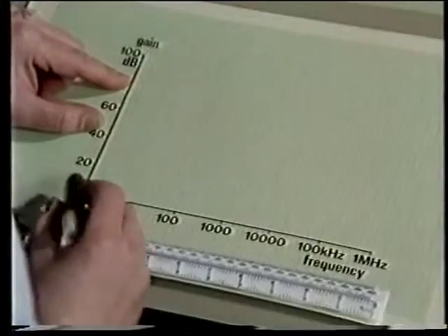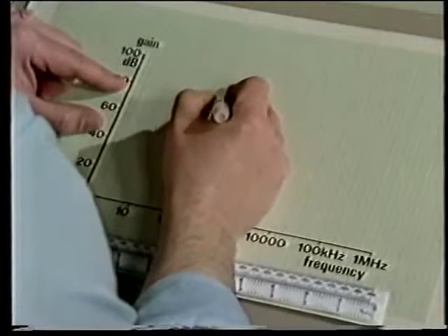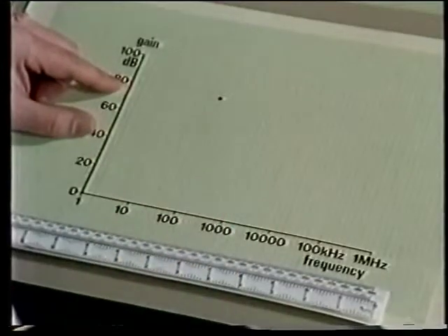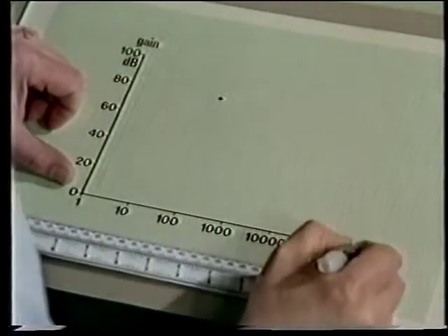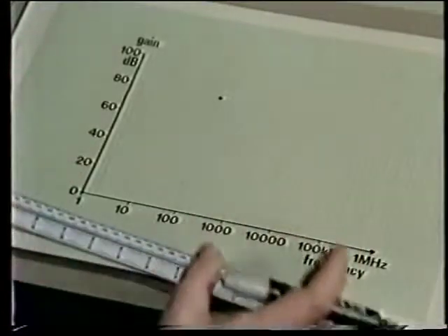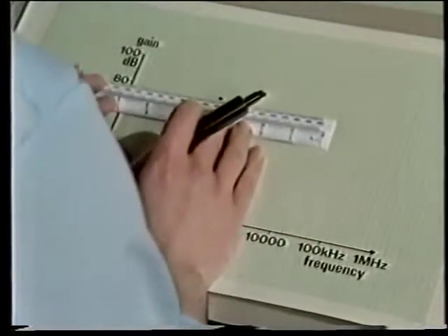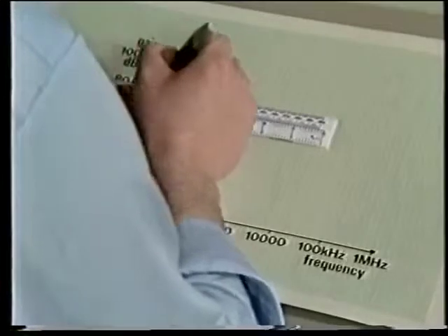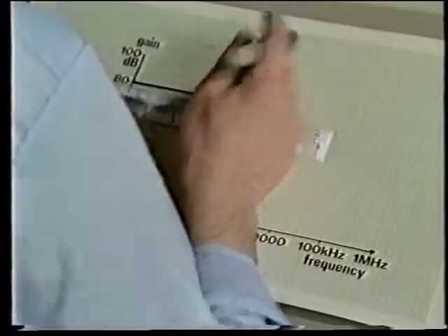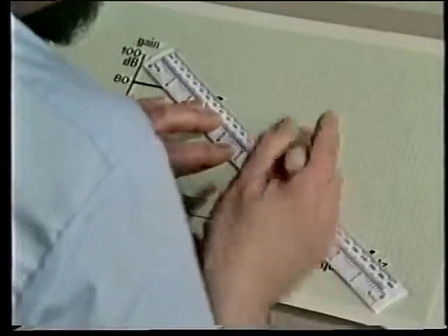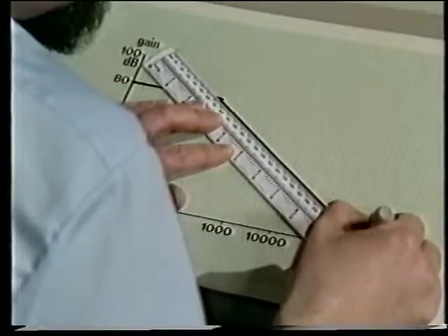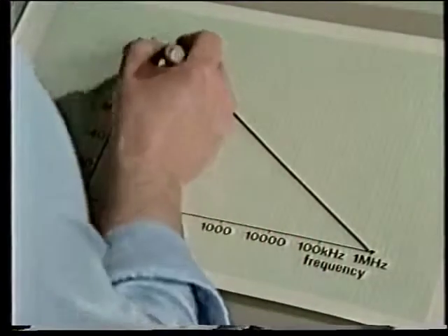Right, Nick, can you please sketch and label this first curve? Well, the horizontal bit was at a gain of 80 dB, and the 3 dB frequency was at 100 hertz. It's about here. And it was 0 dB at 1 megahertz. I'm going to use just a straight 2 lines to approximate the frequency response of the amplifier. And I'll label this open loop.